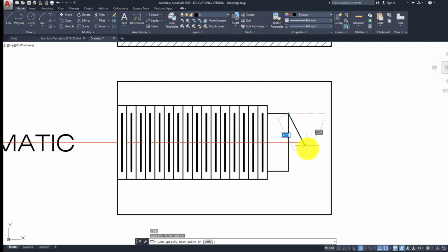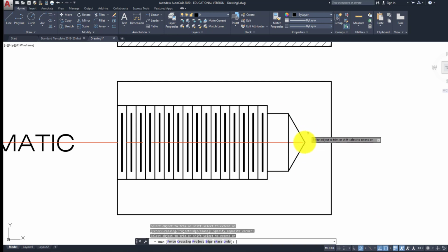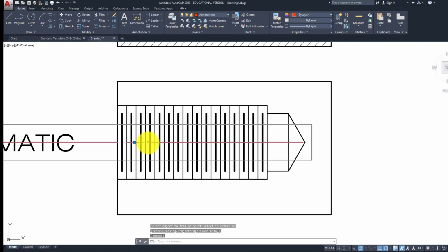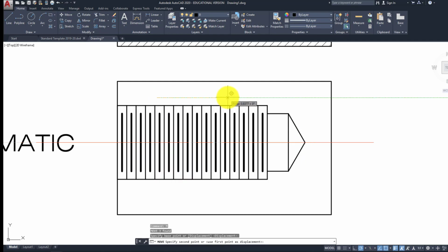And then we show the point, which we'll do our 30 and 30. Make sure that's on, 30 and 30. That represents the drill bit point. Should always show that because it might affect your part or whatever you're making.